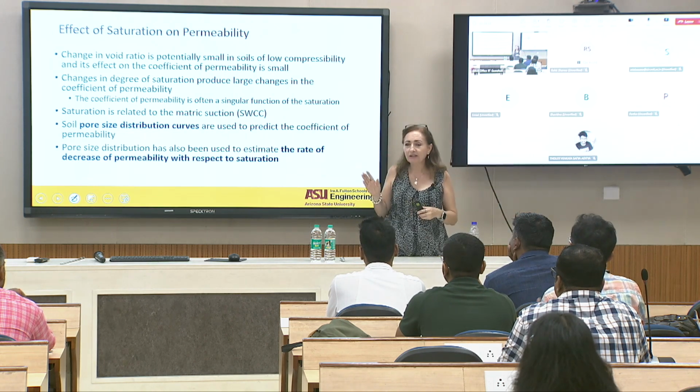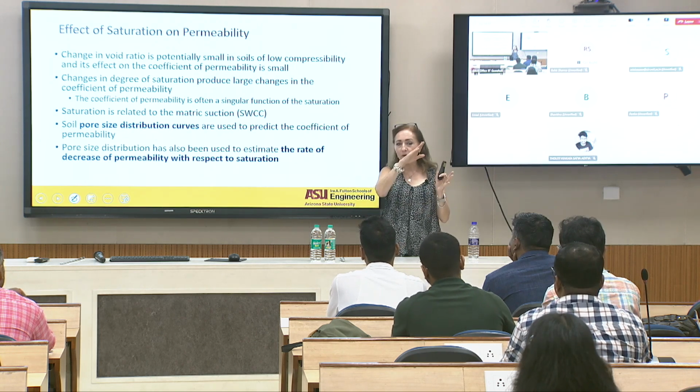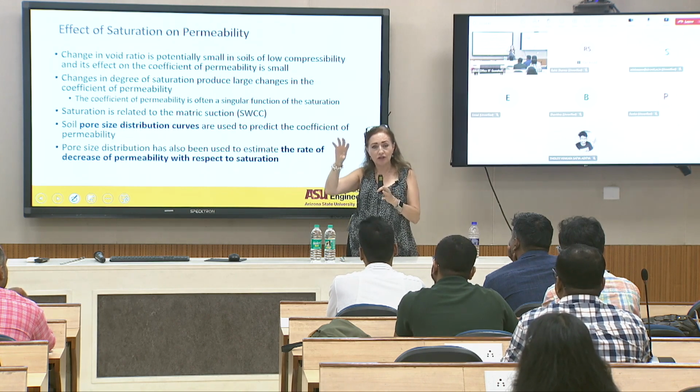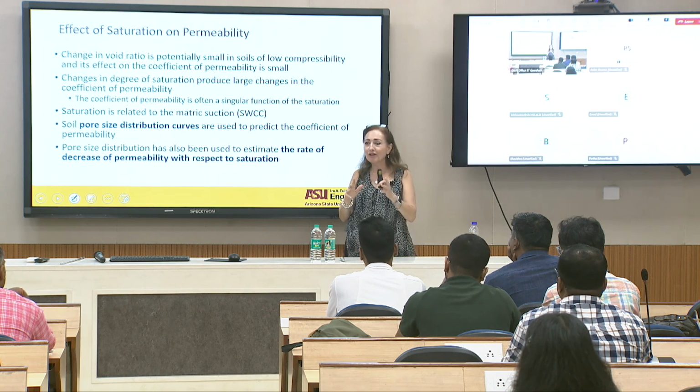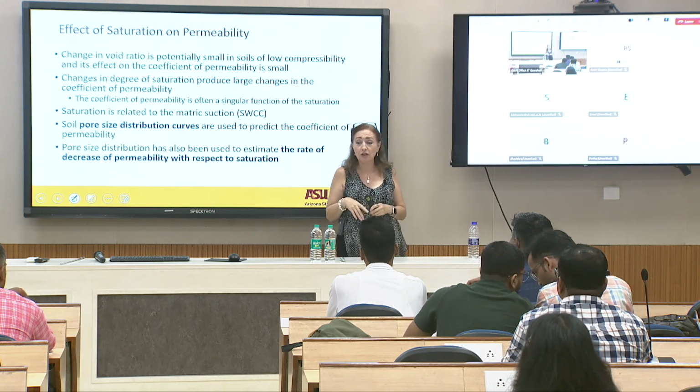And I didn't bring the same scenario that Professor Barat is showing here for the grain size to the SWCC, but we have the same summation of pore sizes, where we can just use the Childs and George method to go from the soil water characteristic curve to the hydraulic conductivity.